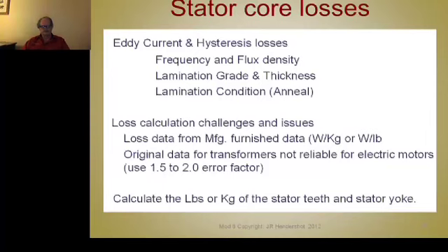But what they concluded is that there's a difference in core losses between lamination strips or Epstein samples that have been sheared and either annealed or not annealed. They test them in all conditions, whether they're annealed or not, but the only stress they're subjected to is the shear stress down the sides of these samples.